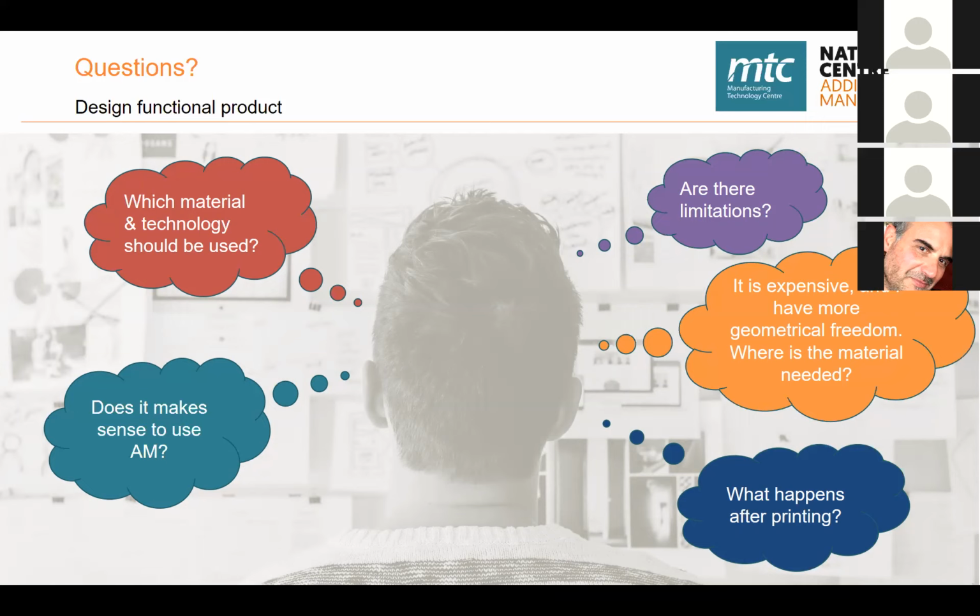Well, yeah, lattices is one of the geometries that are capable of being produced by 3D printing or additive, and usually you should use them when you want to lightweight some areas, because the good thing about lattices is that we get almost the same performance of the parts, but with less weight. There are some other challenges behind that, but usually they are used in those areas.